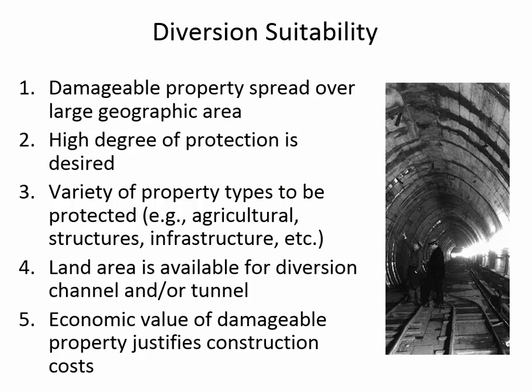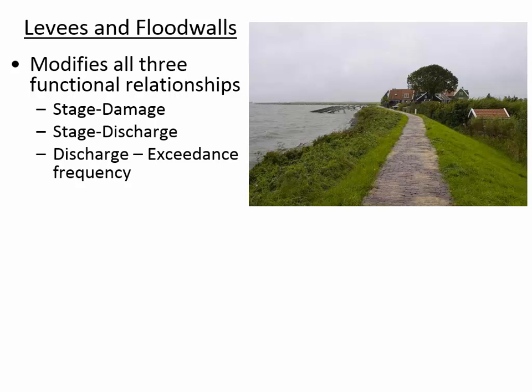So a diversion is likewise the same as with a reservoir, suitable if you've got a large area and you want a lot of protection. But one of the really important things to look at when you're considering whether to use a diversion is whether the value of the damageable property justifies the construction costs, because these can be very costly to put in. The analysis of how much money is going to be saved versus how much it costs, plus the time value of money and the probability of the damage occurring, is a complicated analysis that has to be done. Here's a picture of a levee.